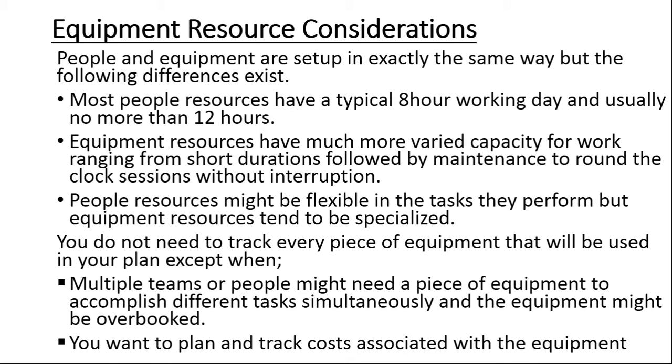When we look at work resources, we see we have got people and equipment. These two are set up in exactly the same way in MS Project, but there are certain differences between people and equipment. Firstly, most people resources have a typical 8-hour working day, and they don't usually work more than 12 hours, whereas equipment resources have got a varied work capacity, which can range from short durations, and after that you